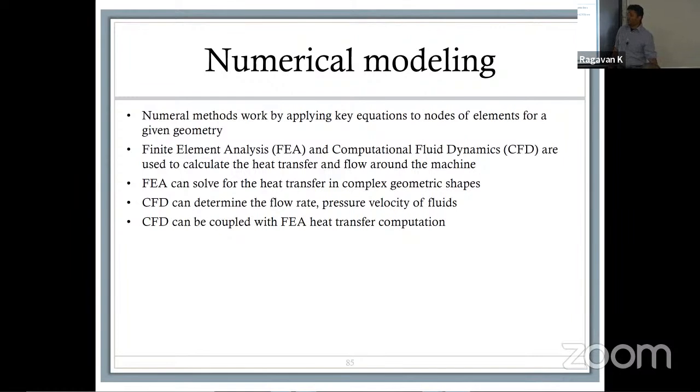So in our case, the motor actually was designed. So what we were trying to optimize was not the fill factor. We were trying to optimize the cooling. So we had an existing motor, and we were trying to figure out how much power we can run for the given coolant. We modeled the channels out to see what the coolant would need to be. We could not change the cooling loop either. The only thing we had control over was the flow rate and the material that is flowing through.